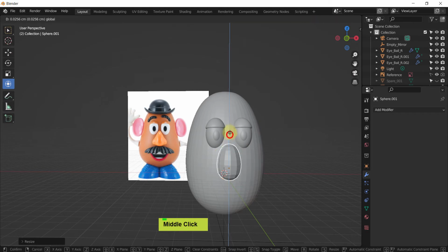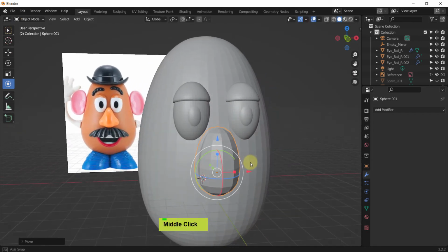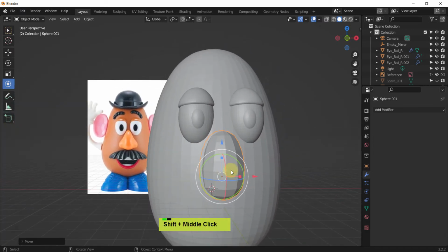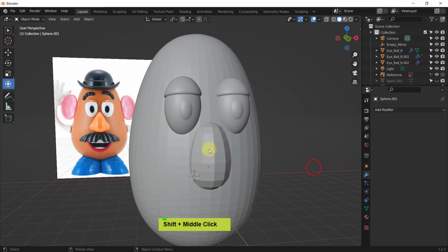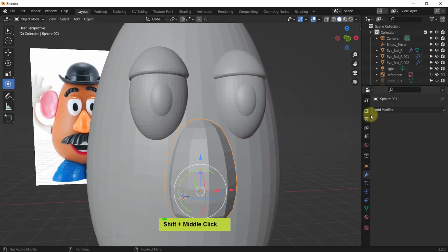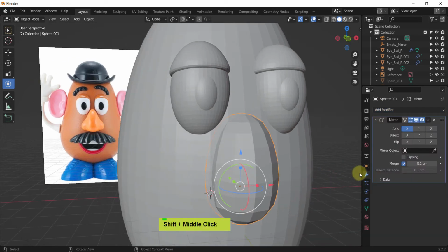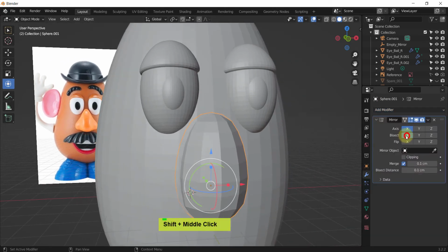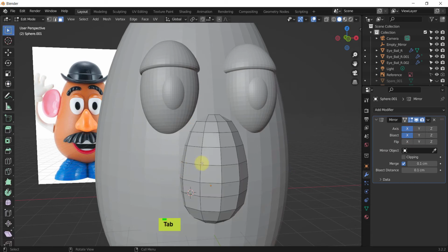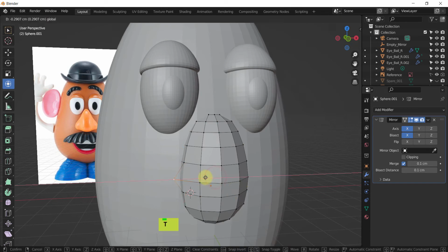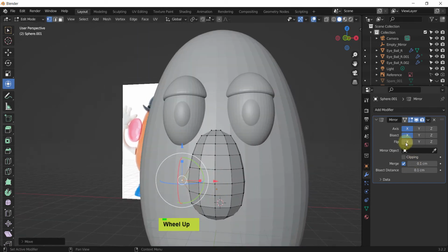Okay, I think the proportion is right. So that's what we will do. And before going crazy, I will apply a mirror modifier, but this one's a little bit different now. So modifiers, mirror modifier, but a couple of settings will be different. So what does it mean? We will apply bisect, and the reason we apply it, so let me go to vertex mode. Here's a vertex. I can move and Shift Spacebar, and Shift Spacebar T. And now if I move this, yeah, bisect should be flipped.